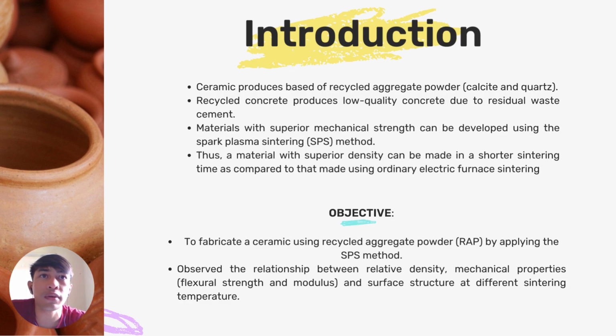So, in order to develop a ceramic compact with high mechanical properties, this experiment is using the spark plasma sintering (SPS) method. This SPS method, which sinters raw material powder within a graphite mold under compression pressure, lowers the sintering temperature and produces material with superior mechanical properties. The benefits of the SPS process include low processing time, high density, high purity, and improved mechanical properties.